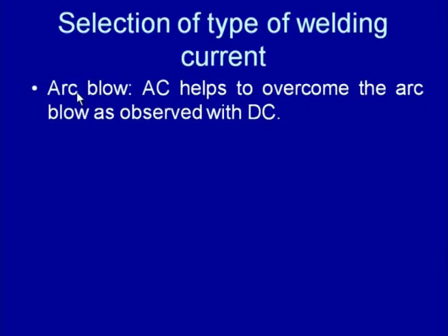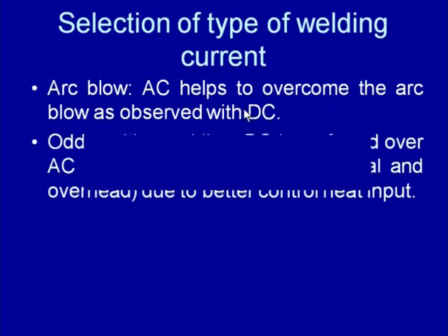Further, AC is preferred when arc blow is observed, which is commonly observed in case of the DC. So, in case of the DC, when arc blow is observed, to take care of the arc blow, to avoid the arc blow, AC is preferred.